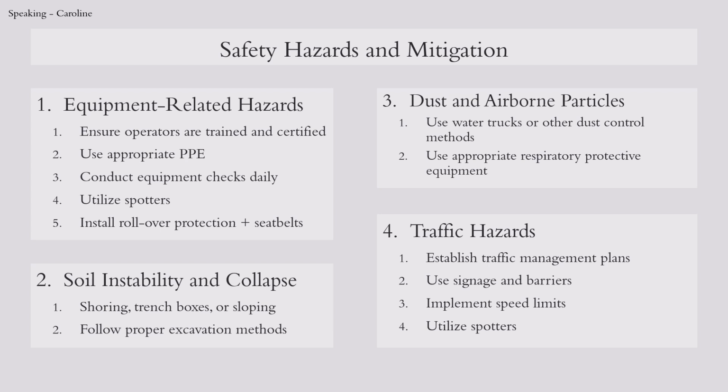The second is soil instability and collapse. This includes shoring, trench boxes, or sloping, and to follow proper excavation methods.